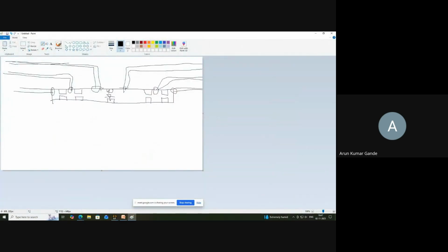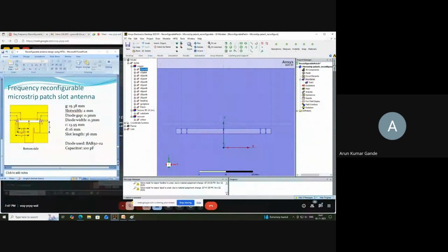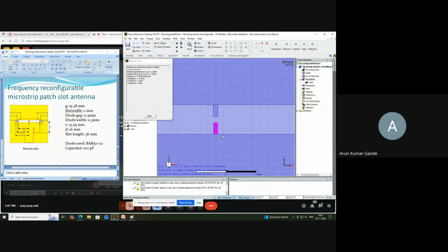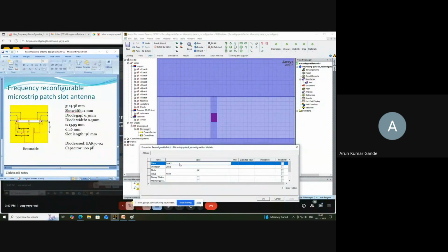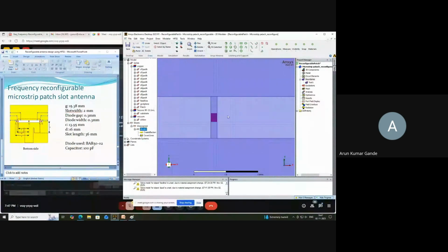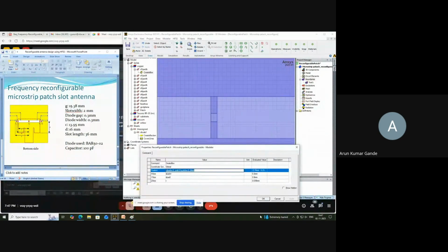So we have made all the diodes now. And simultaneously I make this rectangular sheet here for defining this diode. So let me take that. I'll first draw a rectangle here, right? And this rectangle I'll name diode 1. I'll say okay. And here the position of this I'll take it from here. And then here I'll put it as D and W, and length is slot W minus 2 into D pad L, right? And say apply. So this has to move in the positive direction.